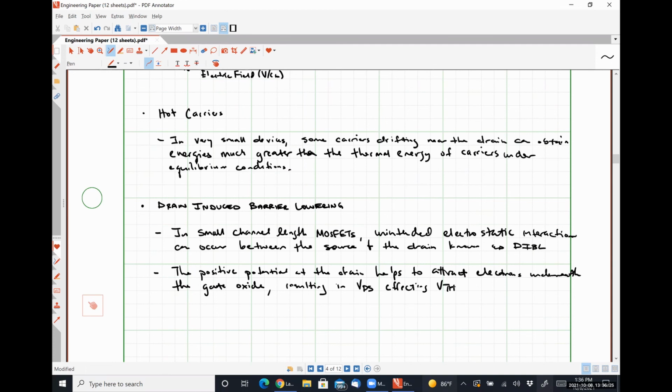Another issue not covered in our textbook is that the smaller the things we make, the more prevalent the effects of heat transfer become, because we are approaching places where the thermal voltage is on the same order as the signals we're looking at. So how do you tell the difference between Brownian motion and you actually trying to send a signal through this thing?